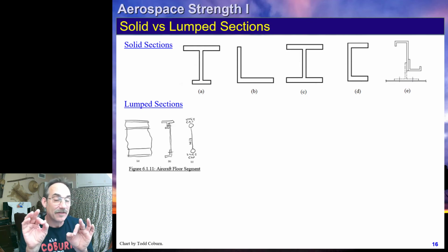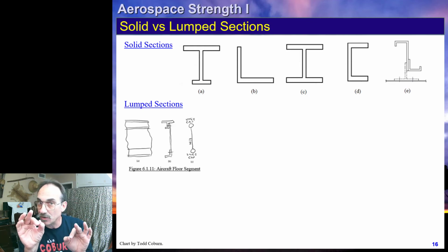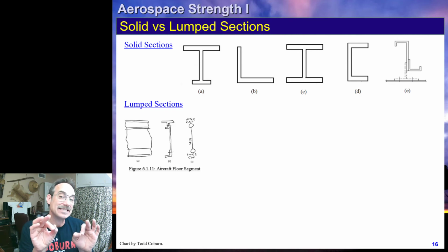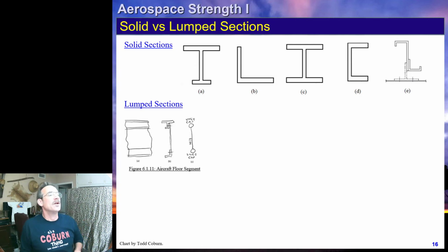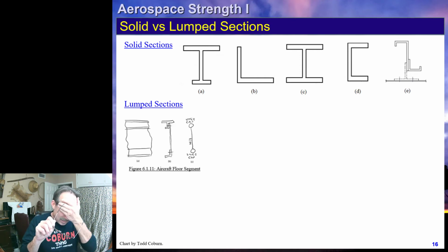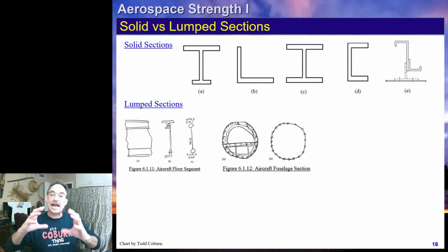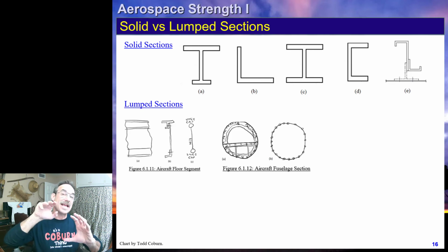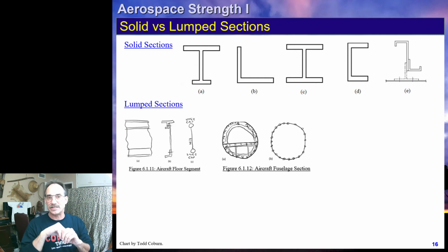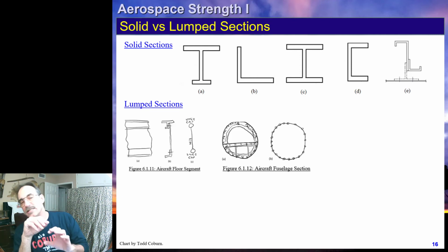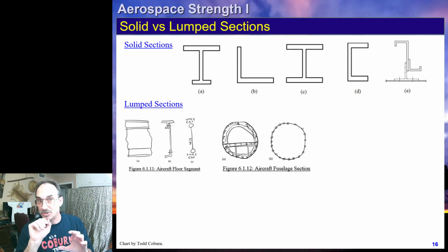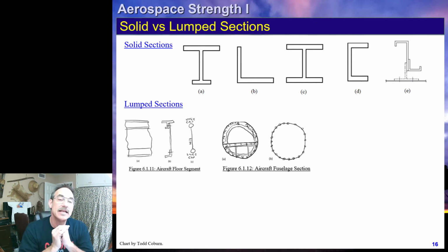This greatly simplifies our analysis. It is important you spend enough time understanding this method of analysis so you don't flub that up, but it's actually a simplified form of analysis. Okay? And we're going to be seeing this increasingly throughout 326, through our Structures 1 class. We'll also see it in our Structures 2 class. We see this same lumped assumption when we're analyzing fuselages, where the stringers act like lumped areas and the skin basically carries, although it does carry hoop and longitudinal stresses, because it buckles at low compression stress, we often treat that like the lumped structure as well.